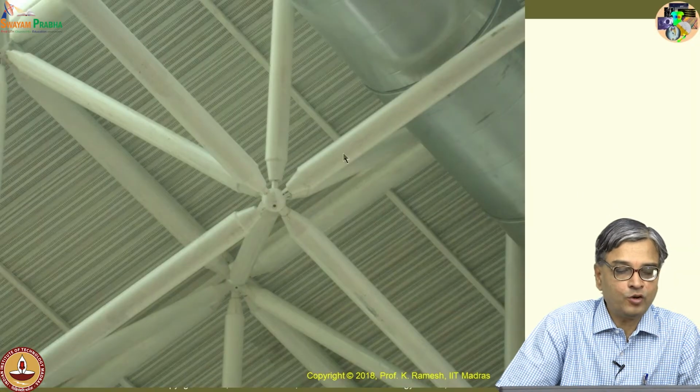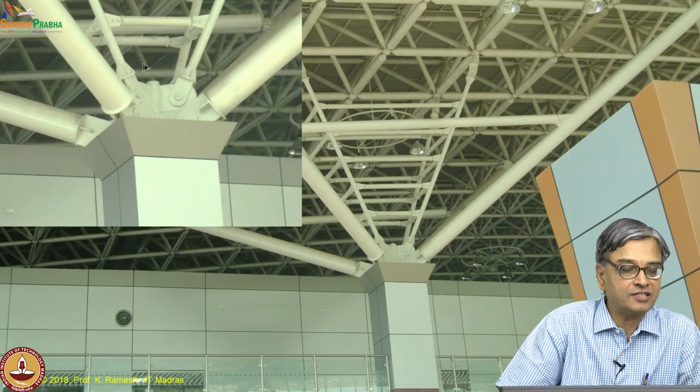And you have this as a space truss. This was there in Chandigarh airport. And if you look very closely, here again you find the members are carefully connected. No member is continuous through a joint, and you can recognize that this is more like a ball and socket joint. That is the equivalent of a pin joint in 3 dimensions. This is another view of it. You can see very clearly that this is joined by pin joints.